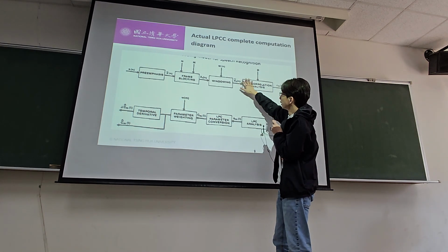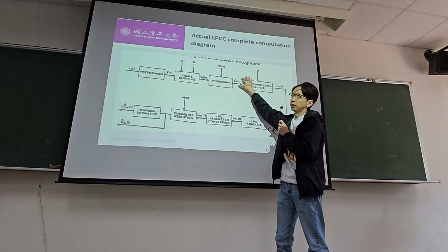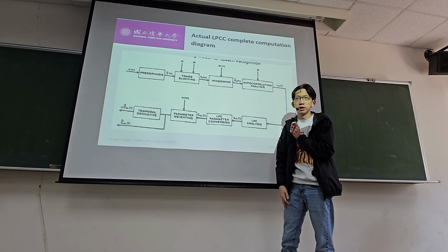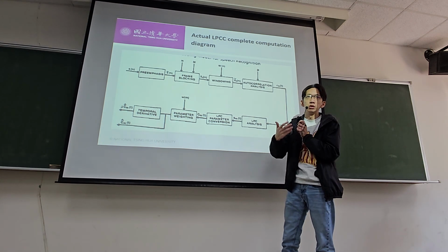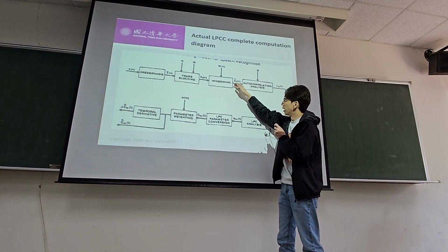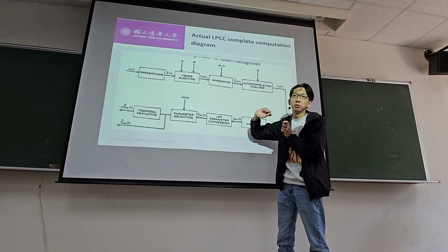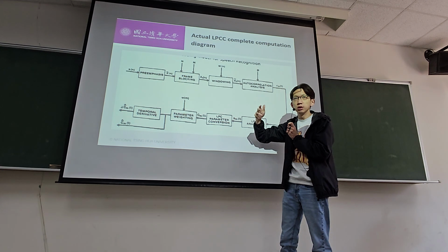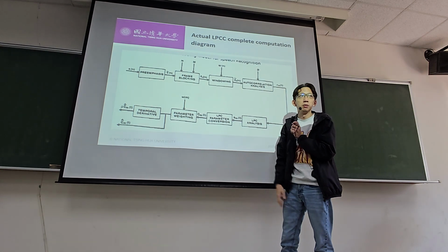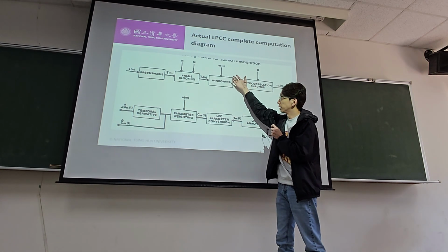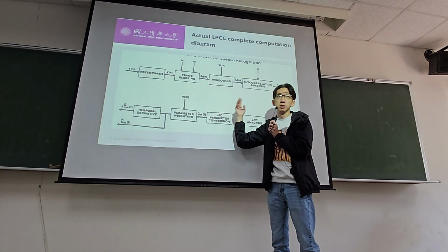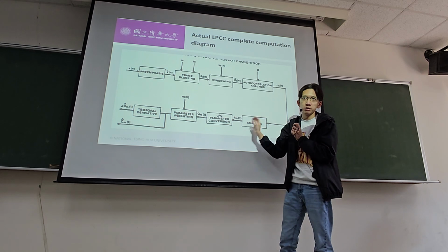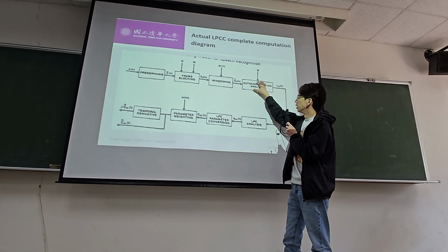Now this part, basically, think about, right, if you take the window, now we start to represent the key information about the signal. You can do time domain feature extraction, or you do spectrum FFT and then you get a frequency representation, or you can do LPC, then you get LPC coefficients, okay, or you directly take the spectrum and then do cepstrum, right? So LPCC essentially, we're in a space of trying to represent the features. Let's do an LPC analysis.